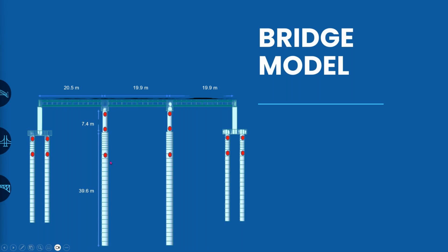So what we'll do is we'll make our piles, or the pile group, such that they are stronger than my column, so that the energy dissipation or the damage will happen in the columns first and not within the piles.